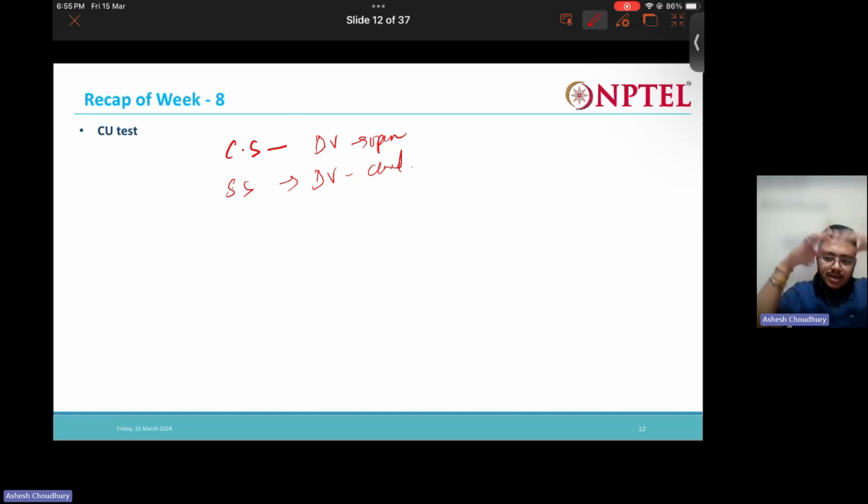For a particular confining pressure, we let the consolidation happen. Then we again increase the load, and then we allow the consolidation to happen. Like this we do. So the CU test is very long, because this consolidation process takes very much time, very lengthy. Similar to the consolidation test, here also we allow the consolidation to happen. The UU test is very fast. This CU test takes very much time.